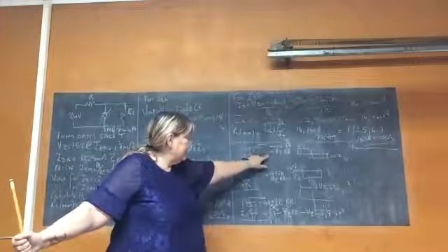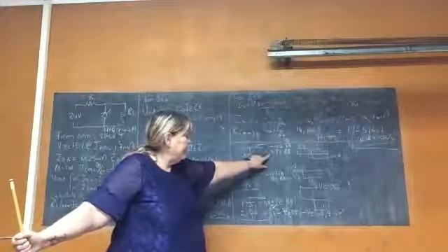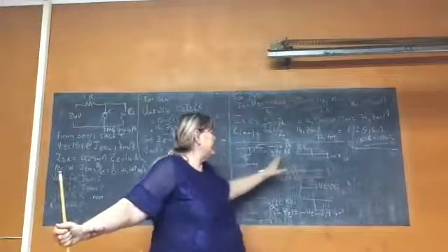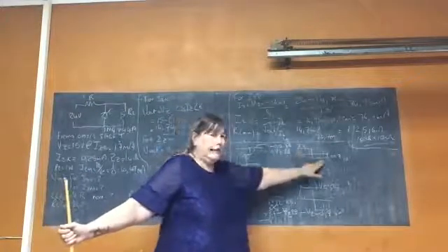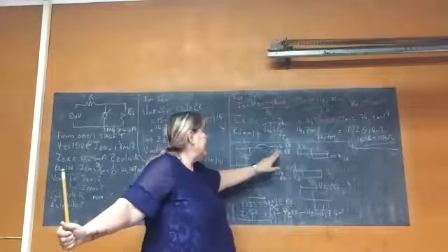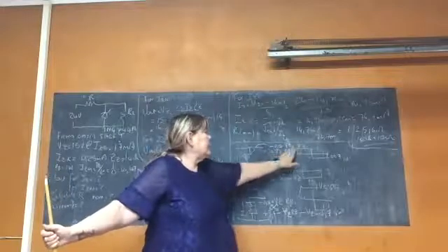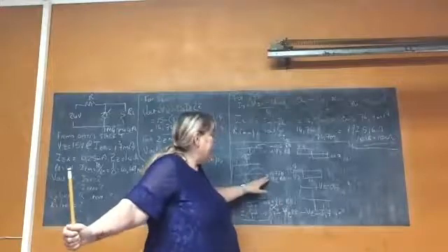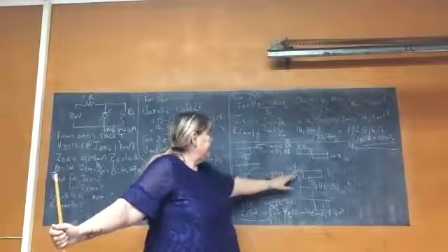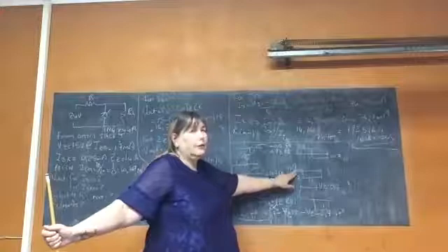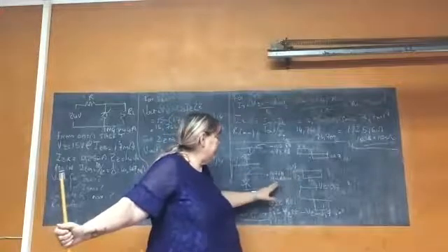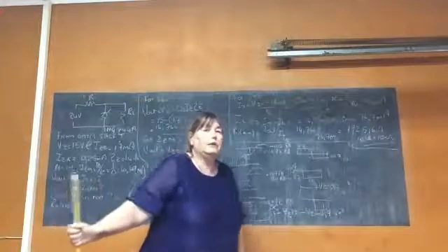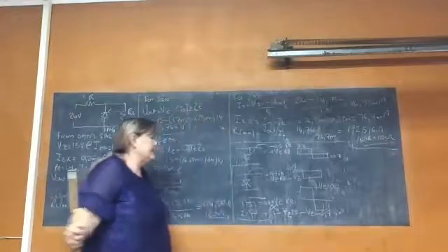Minus 0.7 plus Vz. Minus 0.7 means my negative side will cut off at minus 0.7. My positive side will cut off at plus Vz. Plus 0.7, my positive side will cut off at plus 0.7. My minus Vz means my negative side will cut off at minus Vz.